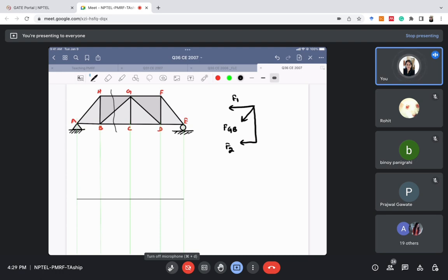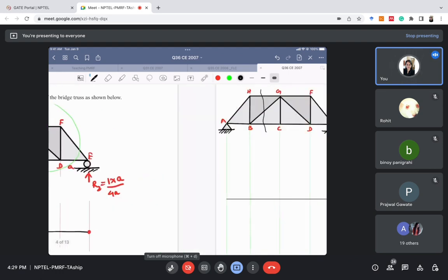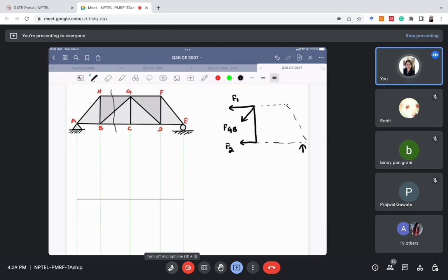Okay. Now, other than that, we do not need to draw any truss. You can simply draw the support here. The support reaction was 1 by 4 here. Okay, so the second step is also done. The first step is we have calculated the reaction. The second step is we have cut the section and we have drawn the section which is in the second part.